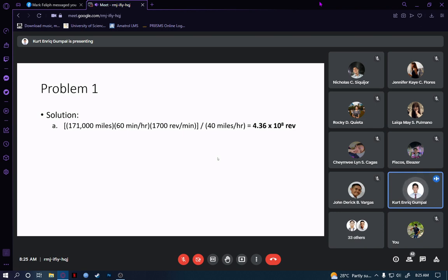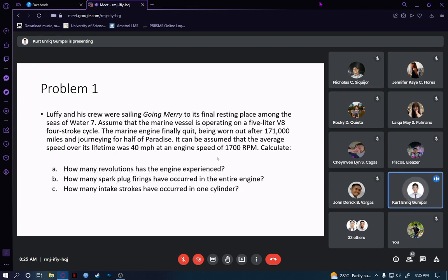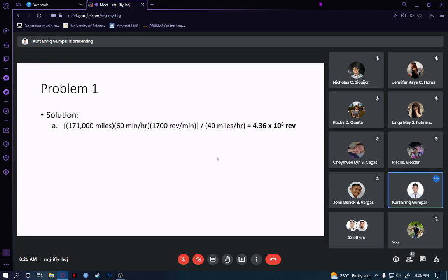Now, the total answer will be 4.36 times 10 to the power 8 revolutions. Again, where did we get it? From your miles, okay? From your miles, I divide it by 40 miles per hour. So I get the total travel per hour. Your miles cancel out. Now, since 171,000 divided by 40 is unitless, and what your problem is looking for is your revolutions, you have to input there the relationship between your revolutions and your speed.